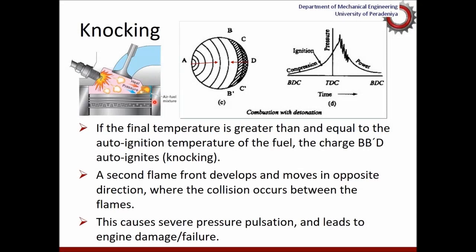One way of controlling auto ignition is retarding the spark ignition timing, or else we can use other techniques. There are a few other techniques also where you could reduce temperature by mixing with exhaust gases. So we call it exhaust gas recirculation and so on.